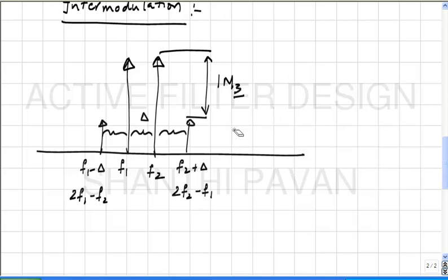You understand? Okay. Now, one way of measuring the linearity of the filter is to keep putting in two tones. This is called the two tone test or the intermodulation test, right. So, you put in a fixed amplitude at the input. The input now comprises two tones F1 and F2 which are closely spaced, and at the output you measure the ratio of the amplitudes at F1 to F1 minus delta or F2 plus delta, and you can move the average of F1 and F2 all the way from a very low value all the way to even frequencies beyond the band edge, right.